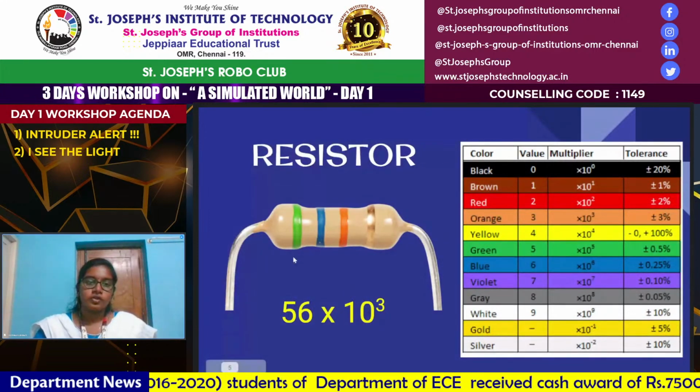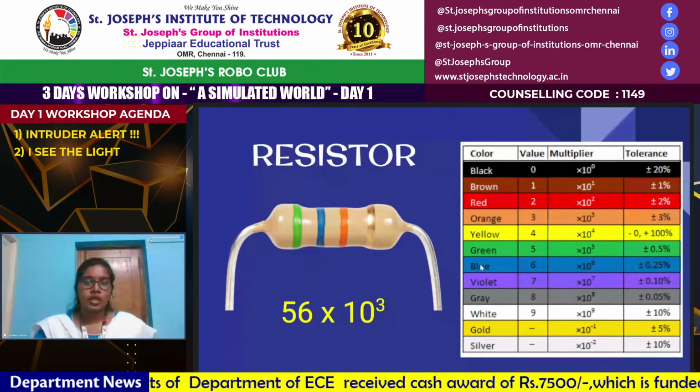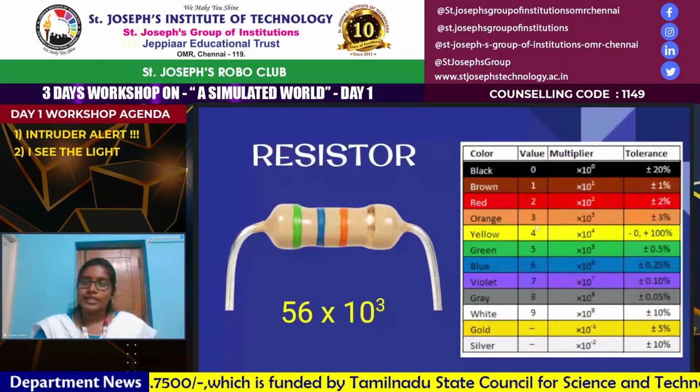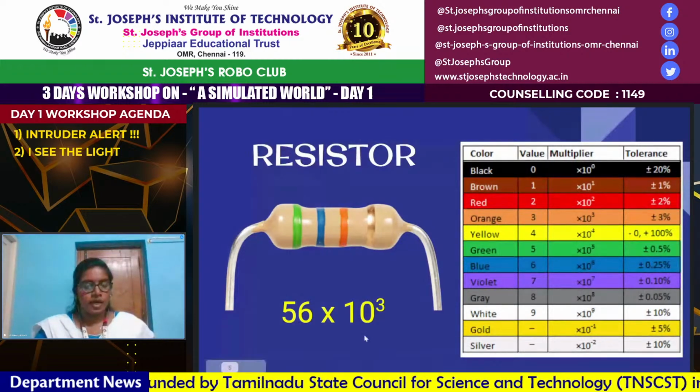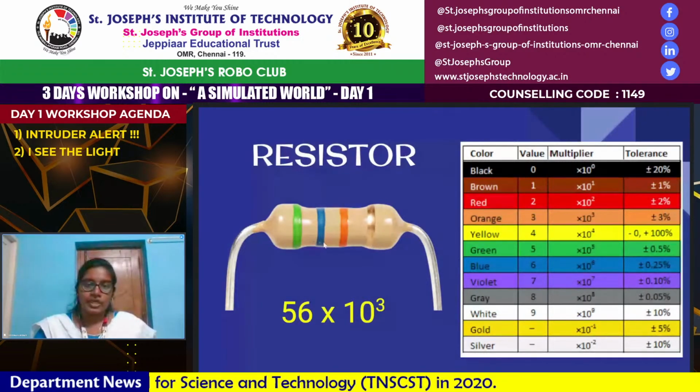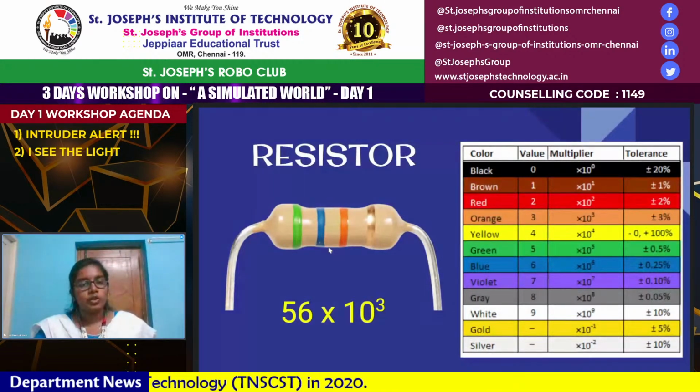The first 2 rings here are green and the other is blue. So the value is 56, and the last ring, that is the orange ring, tells the multiplier, 10 to the power 3. So suppose in the place of green here, I have yellow, and in the place of blue, I have violet. The value will be 47 into 10 to the power 3 for this.